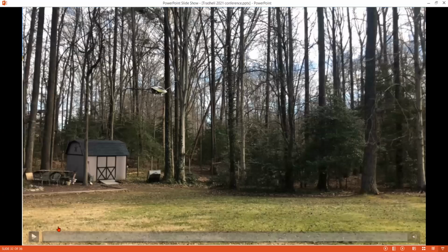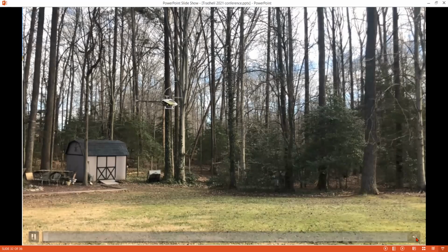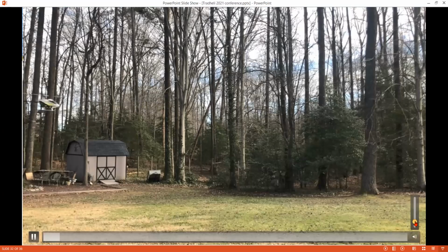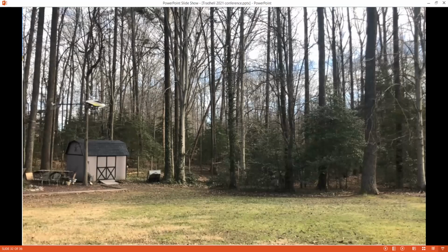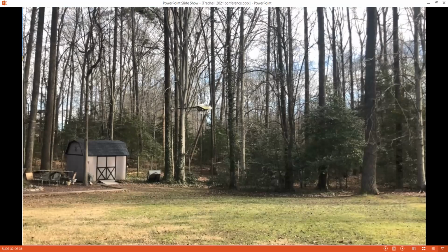All right, so here's a video of early on doing the feed forward test and the angle P test, to give you a first look at what that's going to look like in flight. So hopefully you guys can see this. You'll see it'll nose forward and then nose back and then nose forward. And so I reposition the aircraft. There it goes again, nose back, nose forward. Now again, I've changed this so it does it in both directions. This is from early on when it only did one direction. So it found the feed forward, it's happy with it.